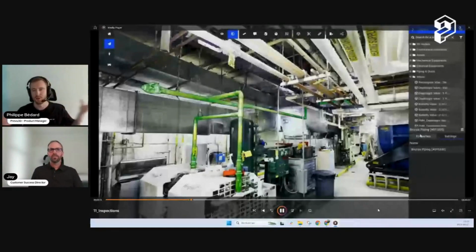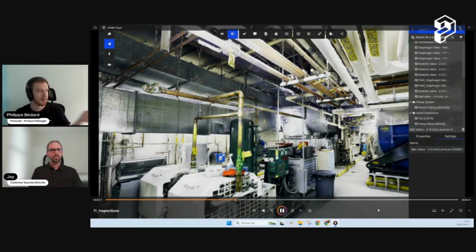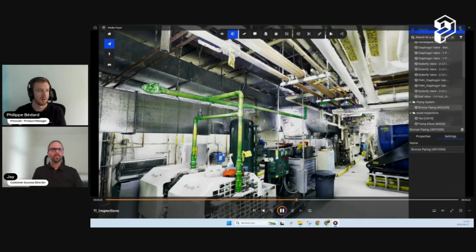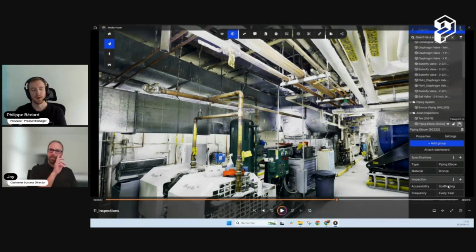Do we need a ladder? What do we need to access those thickness measurement points? So what we did is, I will showcase a video over here, just an example where you can quickly isolate your pipe and then add some points. Like this is the valve, but you can also click somewhere else that would be defined as a thickness measurement point, like over here the corner, and then you can retrieve properties. Do we need scaffolding and things like that to access it?